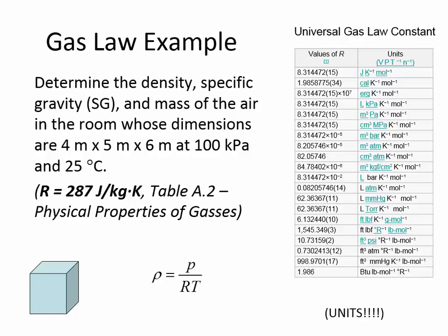Before you start substituting, let me show you a little bit about why we picked these units. Out of this list of all the units we could have chosen for the R value of air, this is the universal gas law, why did we choose joules per kilogram Kelvin? The reason for that is we can take, bring the lights up.